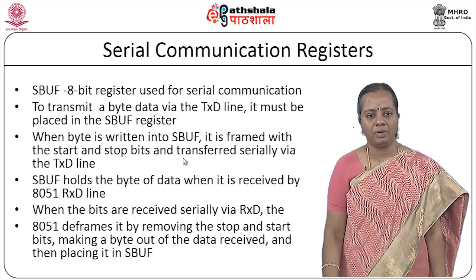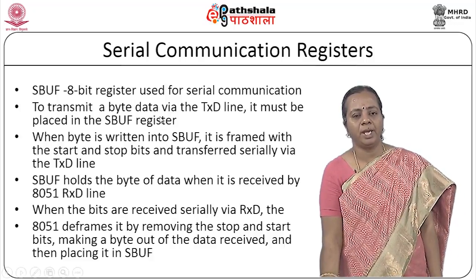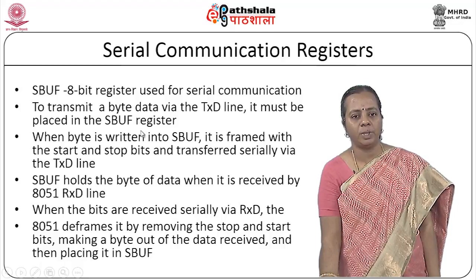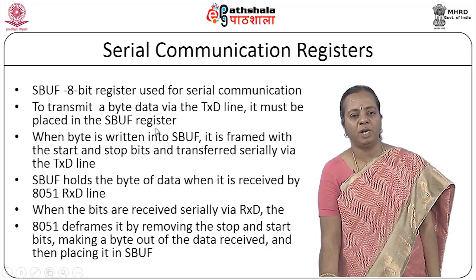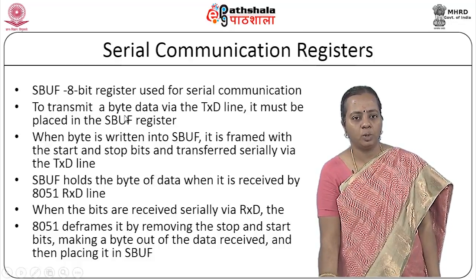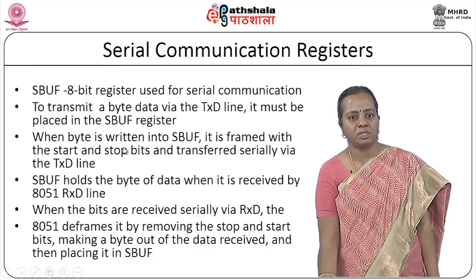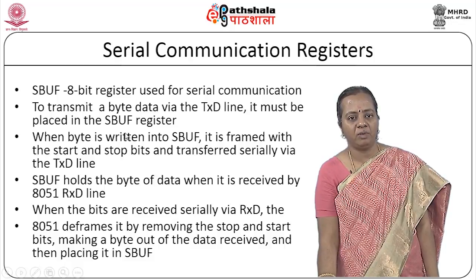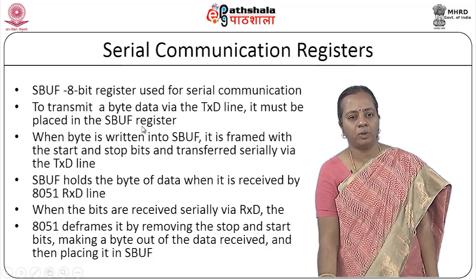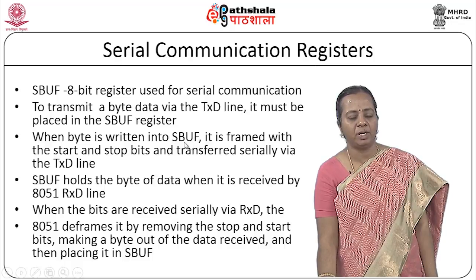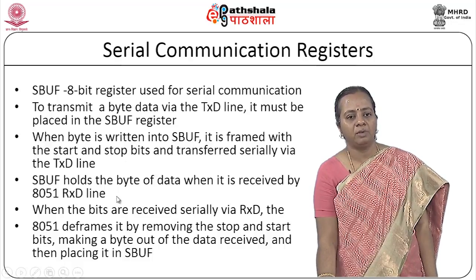If I want to do it that way, somebody has to take care of this process. The data has to be temporarily stored and then transferred. So the interfacing buffer here is the serial buffer. SBUF is the register used as an interface between the data we are giving, processed inside your 8051, to serial mode communication, as well as the serial data we are receiving, which has been combined at SBUF and given as a word to your 8051.